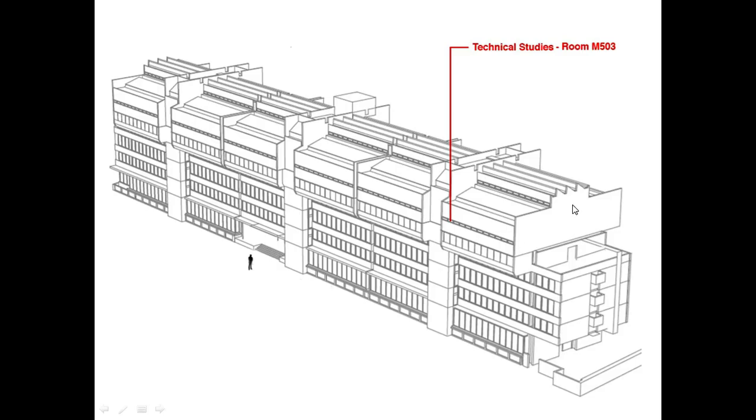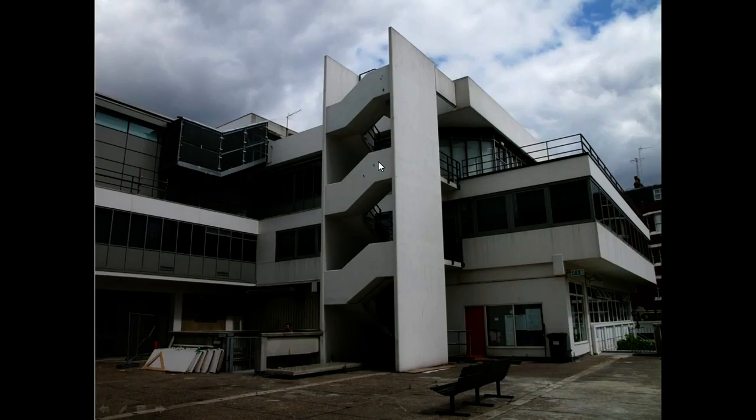So we've got a series of all the floors, everything that's going on in here is taking its load back to ground through this series of, did we say 9 shear walls? All the loads are going back down to here. So everything that connects in between is a series of bridges. In fact, there are literally bridges, because if you're on the top floor here, on the 5th floor, you're walking along a bridge that connects this wall to this wall, and then there's a series of slightly smaller bridges that are cantilevering out in this case, and so there's a kind of hierarchy of structure.